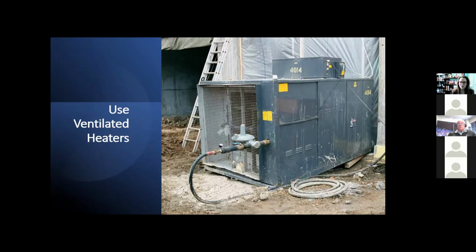The problem I have with that solution is the bond. As a person who used to work in the repair industry, I feel strongly that you're not prepping the surface enough for bond. You'd basically be making a delaminated surface for the majority of these products. What you really want is to remove all of the dusted layer and then apply that sealer so that the dusting doesn't come back. Otherwise, it can come back. And again, it just depends on what the surface of that slab is.